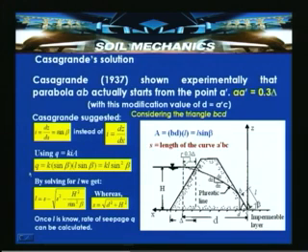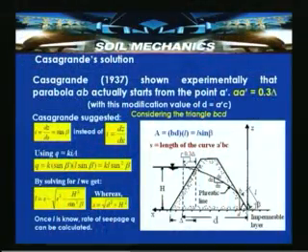So here with this we can now write Q is equal to K sin beta, that is because of the dz by ds into L sin beta. So Q is equal to KL sin square beta. By solving for L, if you again rearrange the variables and then integrate, we get L is equal to S minus square root of S square minus H square by tan square beta,